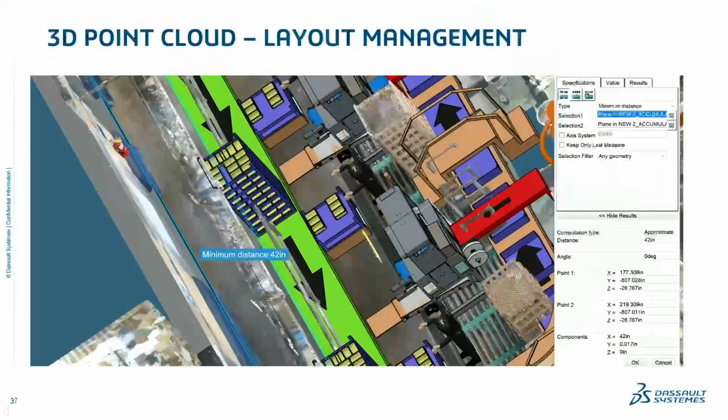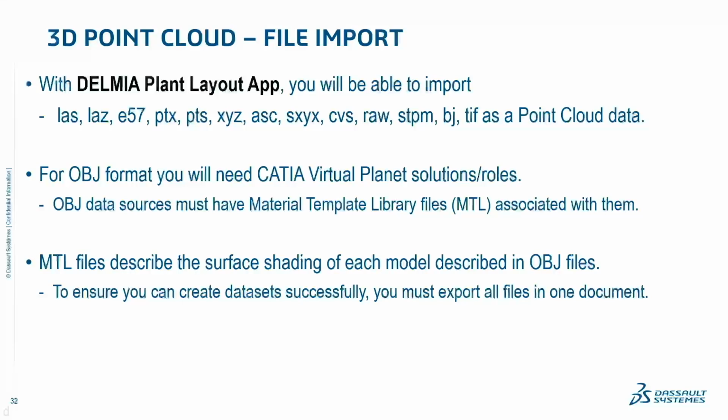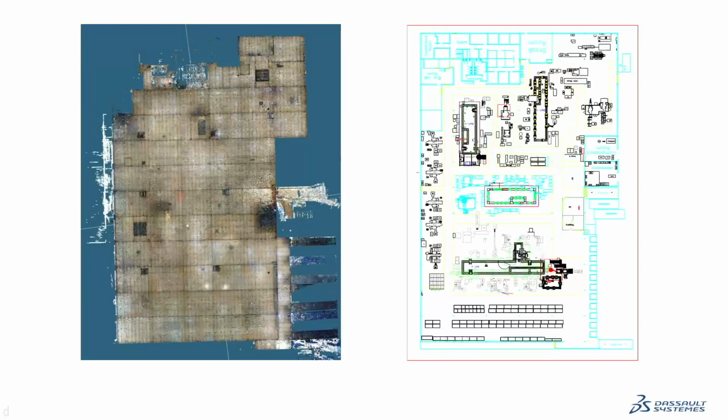If you go back a few, to where it gets the overall, the one where we're comparing the two. Go back one more, right there. If you look on the bottom right-hand side, those are actually van trailers that were backed up to the dock when he was there scanning. All the excess that you see, like the dock trailers, there's an extract command where I can go in there and cut that stuff out and remove it if I want to. Same thing with the roof, like you saw in the other one with the SolidWorks stuff. The first thing I normally do is an extract, cut the roof off and hide it. I can always turn it back on, but it's easy to see, because when you scroll in, the more detail you see. Yes,